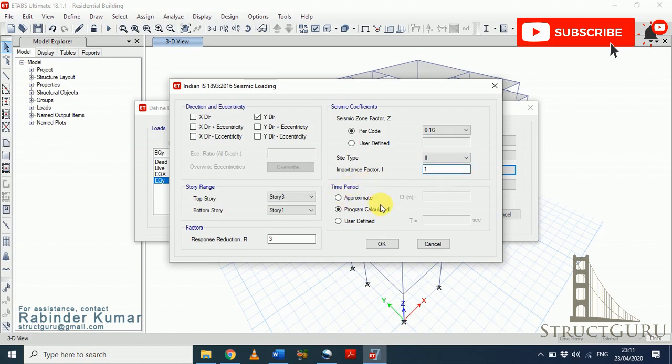For time period, I will always recommend you go for the program calculated value. Don't go for user defined or approximate value, because if you compare with manual calculations, the values will be different, as ETABS considers stiffness into account as well. So always go for program calculated value. Similarly, in story range, some users go from base to story 3 and some users go from story 1 to story 3. Because our base is embedded in the ground, whether you choose from base or story 1, it is fine.